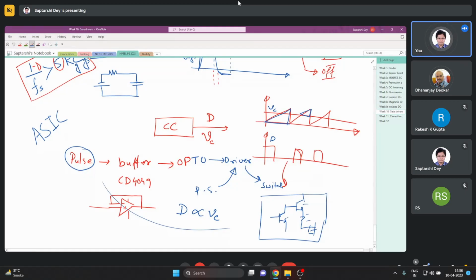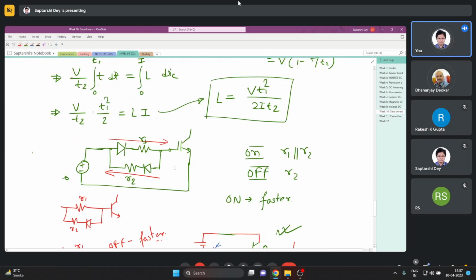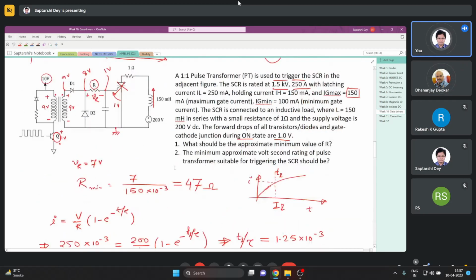Things like that are being done, like there are buck converter ICs directly. You do not need to make a controller separately. You have one dedicated IC for controlling a buck converter. Topology specific, yes. Dedicated ICs are there. Like one IC I just mentioned once today, the MC33153.